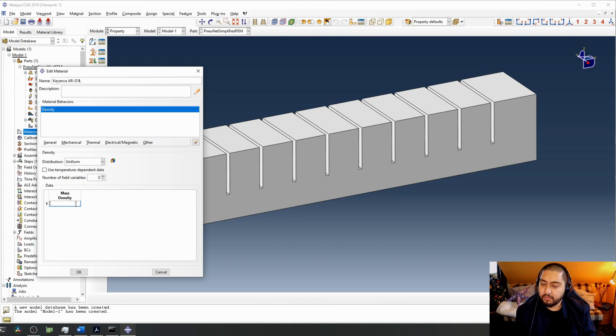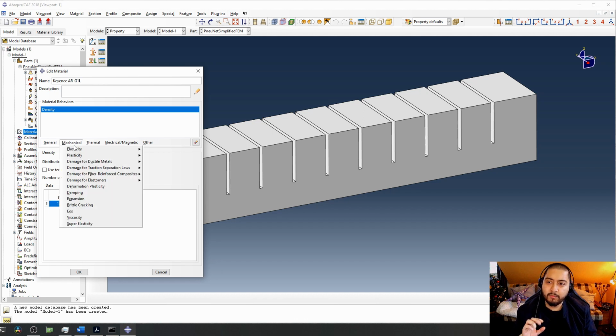So here we are going to define a density of 1.049E-9. As I said, we took this density from tests, and we tested everything. So this is an investigated density. Probably it's going to be similar for different silicone materials, around the same, in between 0.99 and 1.17 or something.